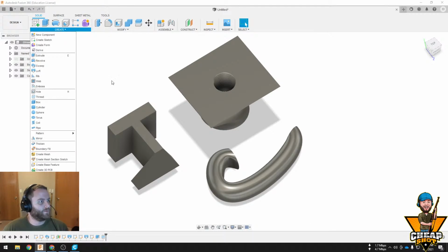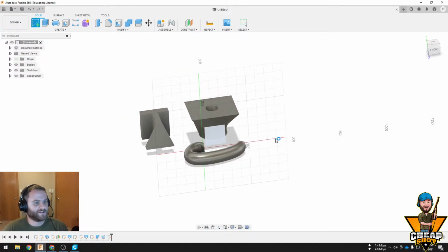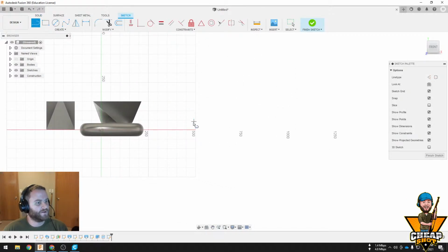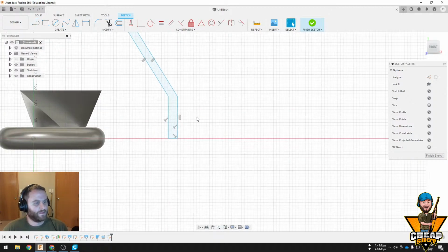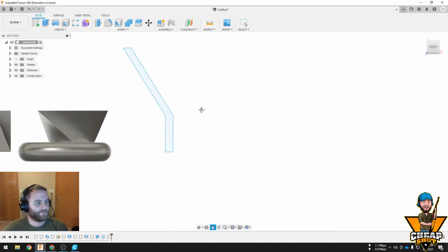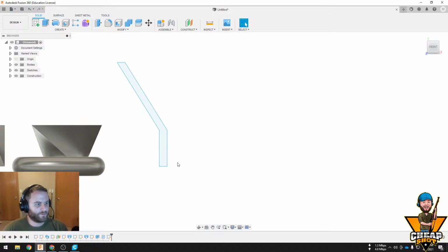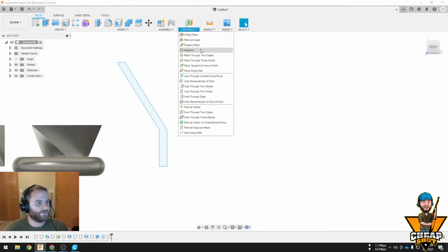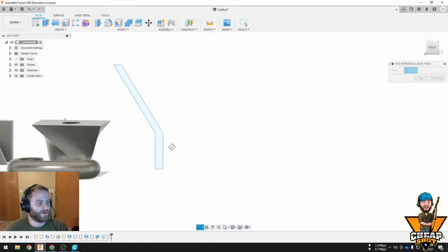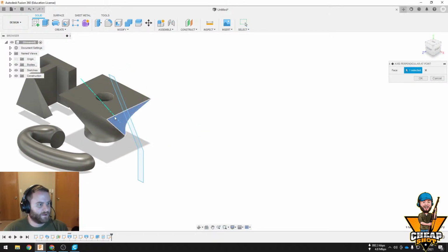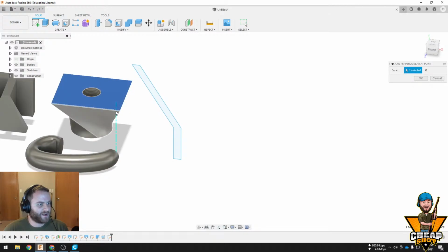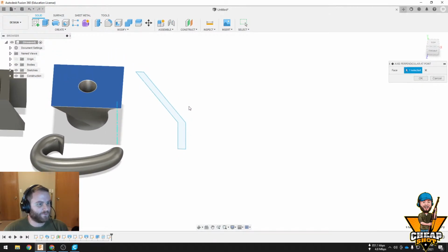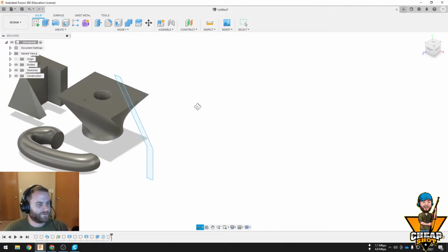So what else we got? We can do a revolve feature. I just covered that in a fast Fusion video. So let's say I want to make a funnel, right? I can revolve this around a plane. Now there's nothing to really revolve it around. I would need to create an axis for it to revolve off of. And I could do it around that. I'm trying to, yeah, like an offset one. I don't really want to do any of those.